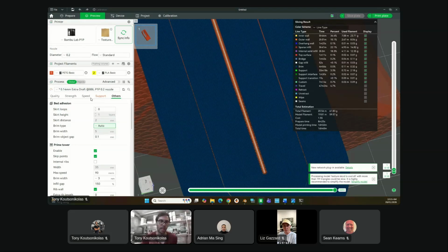That's okay. So just make sure that whatever you do go for has really good bed leveling. This isn't me trying to sell you, I don't get anything from Bambu, but all the Bambu printers have really good leveling when you calibrate them and you've got the right filament settings. So number 1 is the bed leveling, and number 2 is your filament settings. You really want to dial them in, especially for the first layer in this case.